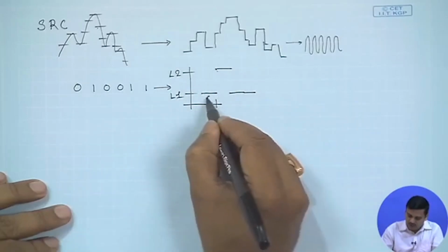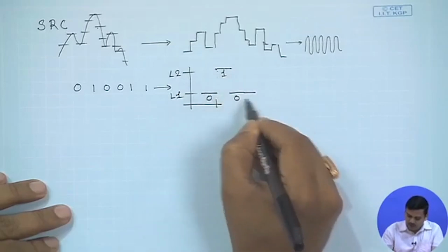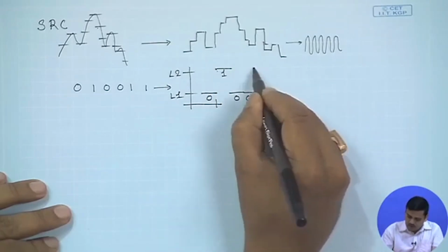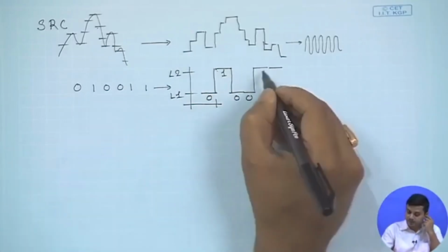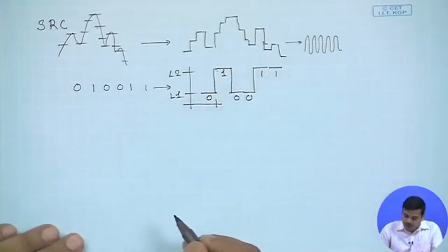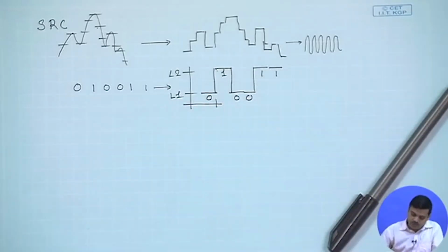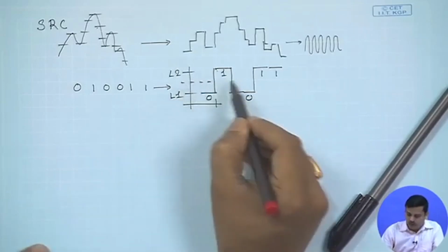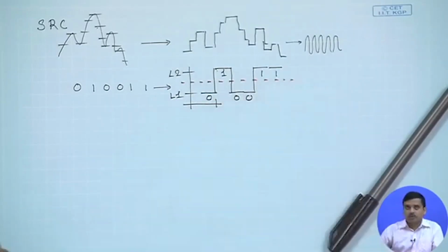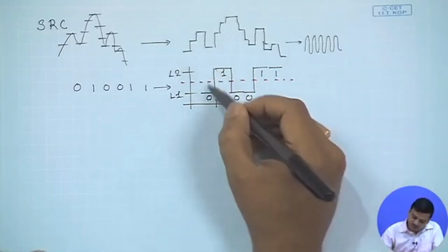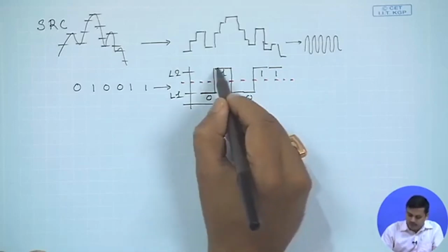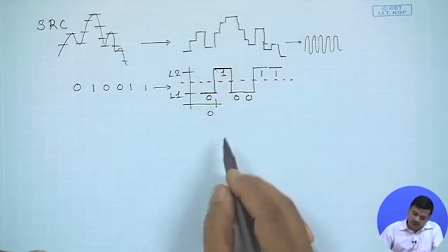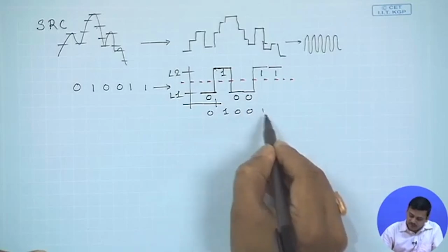So this indicates there is a 0, there is a 1, there is a 0, a 0, there is another 1, there is another 1. This matches with respect to this particular signal. At the receiver, we would have to choose a threshold. If the received signal is below the threshold, I would decode this voltage to indicate a 0, and this level of the electrical signal to indicate a 1, and I would regenerate my signal.